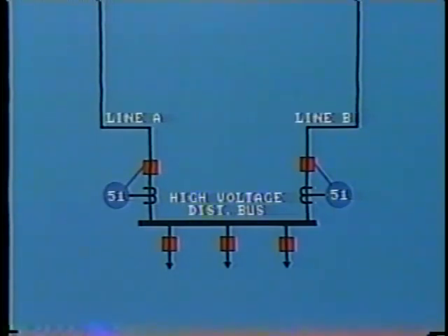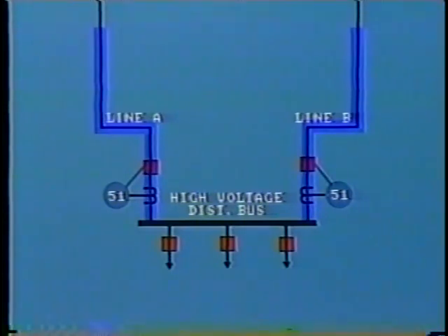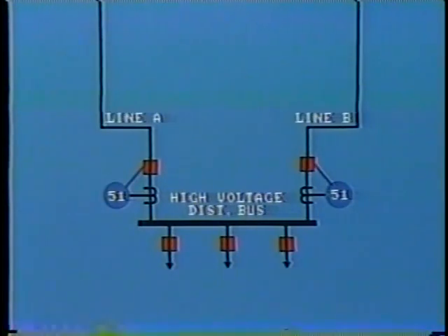When the overcurrent relay senses fault current, it will operate irrespective of the direction of the current flow. Quite often, we would like the relay to operate for current flow in one direction only. Let me show you why. This example shows the high-voltage bus in a distribution substation. It is fed from sub-transmission lines which are part of a continuous loop. In this arrangement, current may flow in or out of either sub-transmission line, depending upon conditions or system configuration in other parts of the loop.